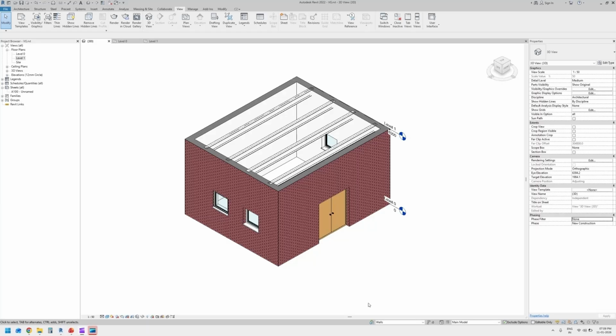If you are working with design options in Revit and suddenly your elements disappear, it's because design options and visibility graphics can silently hide your model. Design options are used when you want to show multiple design possibilities in the same project. Here, what we have done is we have created the floor in a separate design option and the rest of the elements within the main model. So if you try other visibility graphics options to turn on the floor, you will fail.